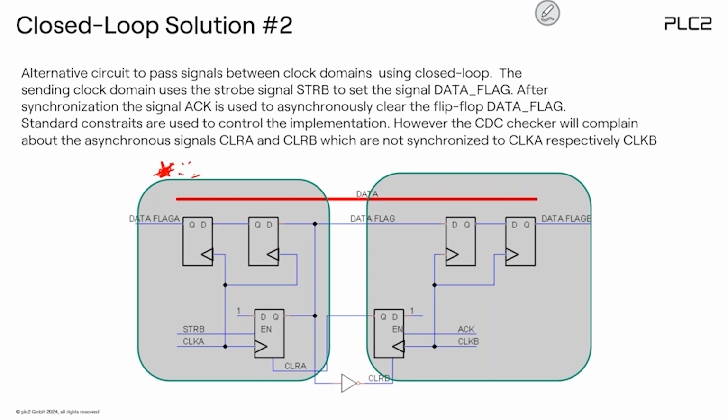Then you just place a strobe here. Say, just enable here, you just provide a 1. So you get a 1 here. This one will be synchronized. Because it's synchronized, this signal can be used as an enable for the data, because this event is much later in reference to placing the data. So this is always safe.